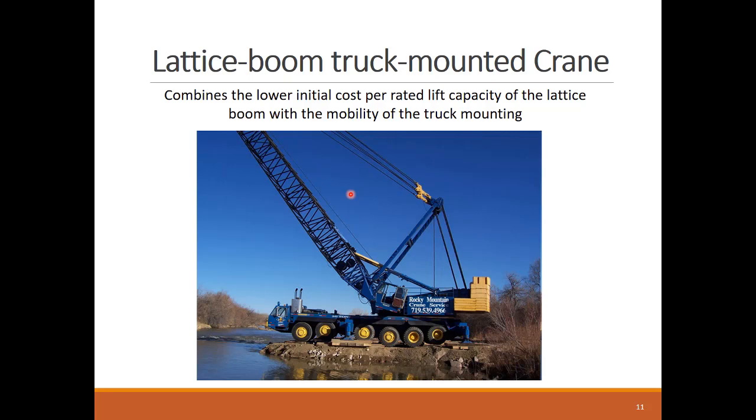Lattice-boom truck cranes are ideal for steel erection, port and bridge work, and are known for quick line speeds. The lattice boom takes a long time for assembly and setup, but their lightweight, efficient truss lattice design makes them more affordable than the telescoping boom for the same load.